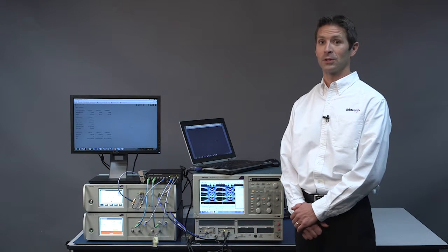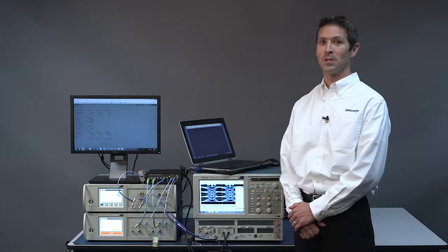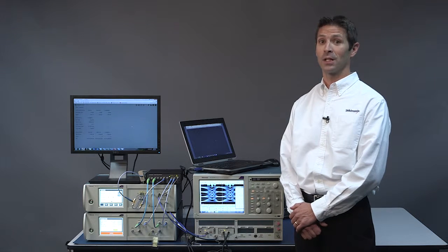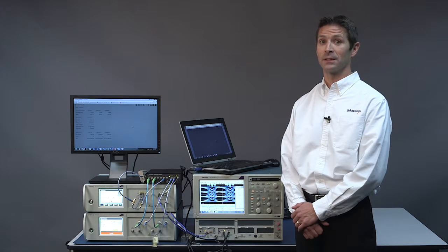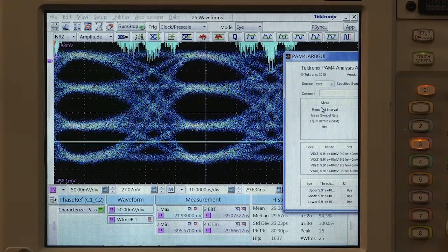I have employed the skew adjust capability of the PPG that is specific to each channel to tune the relative phases of the combined PPG channels and create a very clean PAM4 signal with very high signal integrity and symmetry.